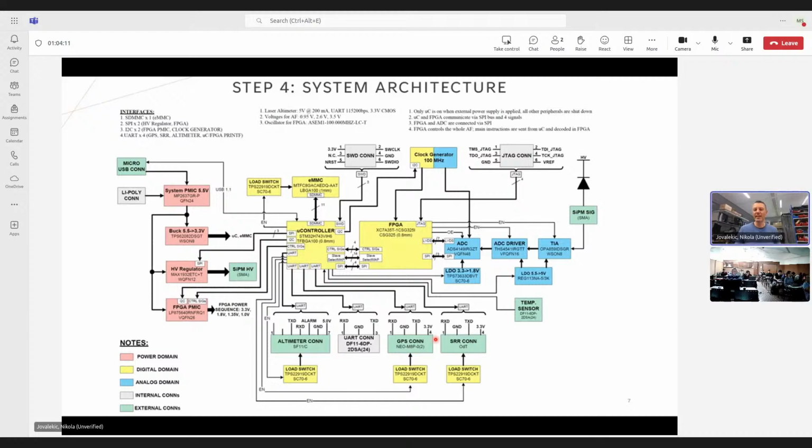All these components here, you can see the part numbers. I also put the part numbers here. You literally need to download their data sheets, go to them, and then see the pinout of the component and the footprint. Are you familiar with the footprint?